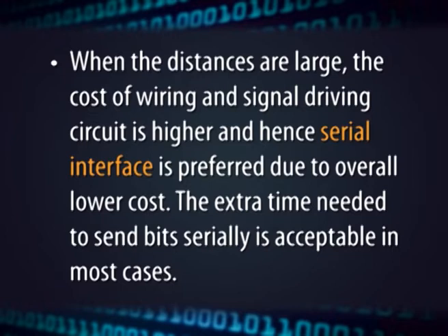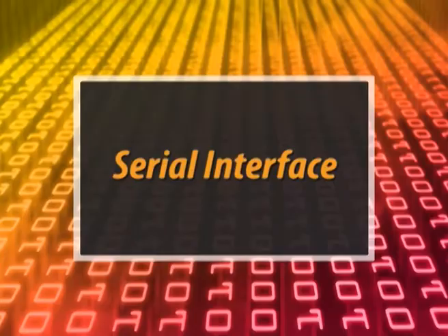The extra time needed to send bits serially is acceptable in most cases. Serial interfaces are popular between computers and modem and computers over distances up to 10 meters, or even sometimes up to 1 kilometer with suitable line driving equipment. Serial interfaces are also popular with devices whose average data rate is a few tens of bytes per second, such as keyboard, mouse, etc., where small additional delay due to sequential bit transmission is not noticeable.